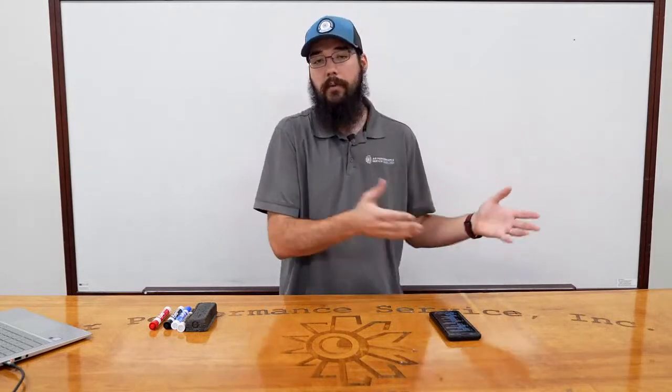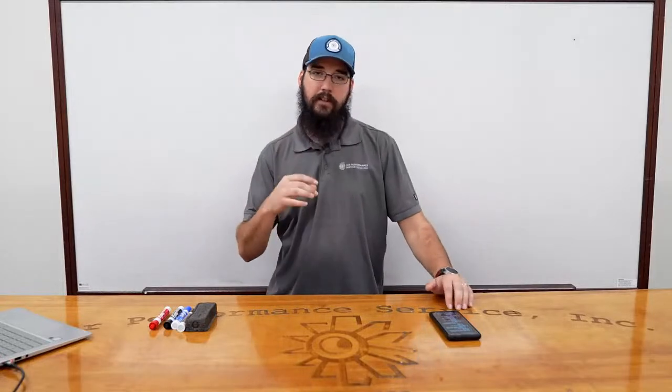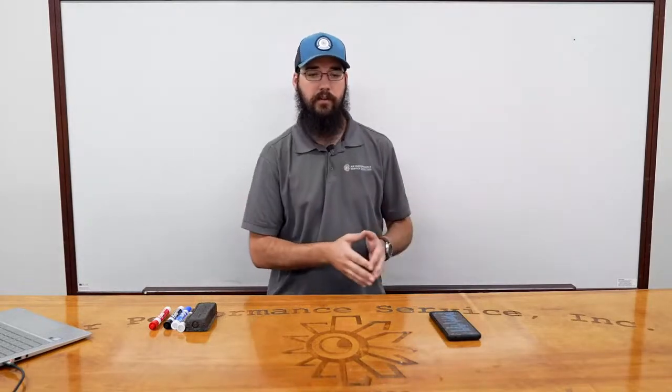Because it may not even be that we have a low return. I mean, obviously we're there because it's not cooling, so you would expect that the return air would be elevated, to whatever degree fits the space. Maybe 75 elevated, maybe 78, maybe 80, could be beyond that. So we're expecting to have a higher load to begin with at this stage. But yet our readings are still showing, like our refrigerant's superheat and saturation on the evap, are still showing low on both ends of that spectrum, for example.